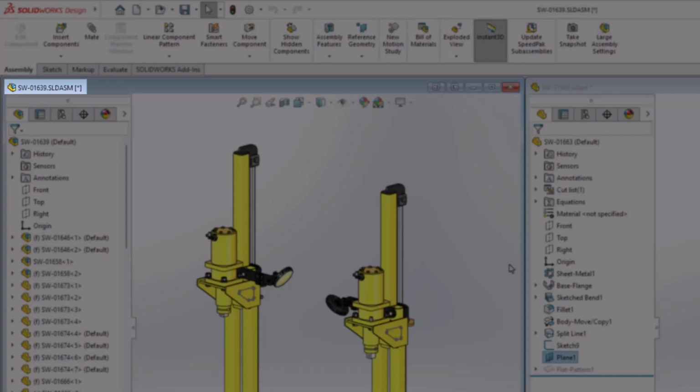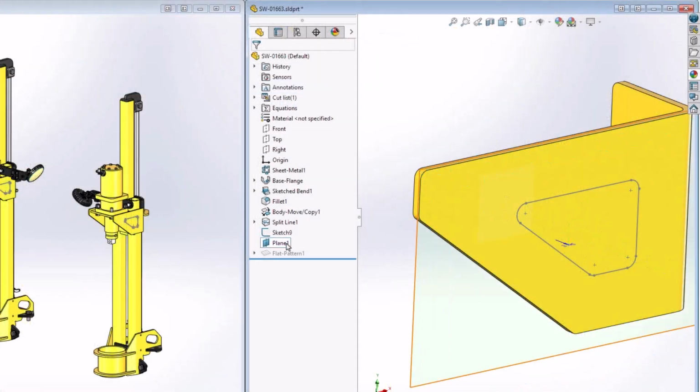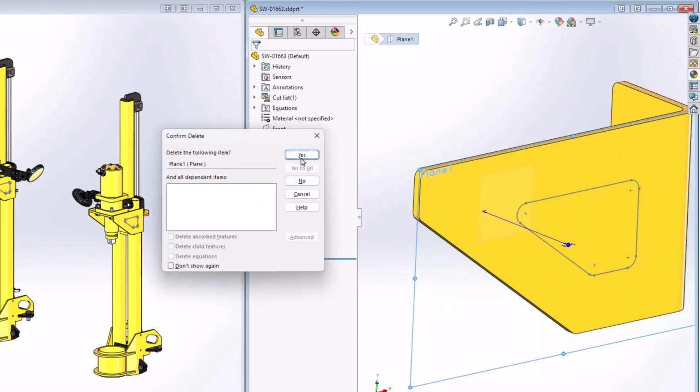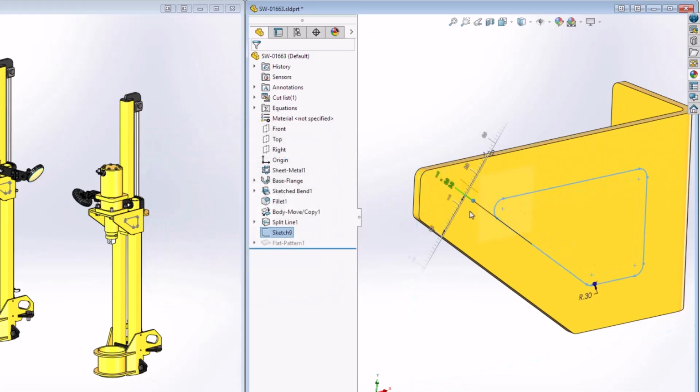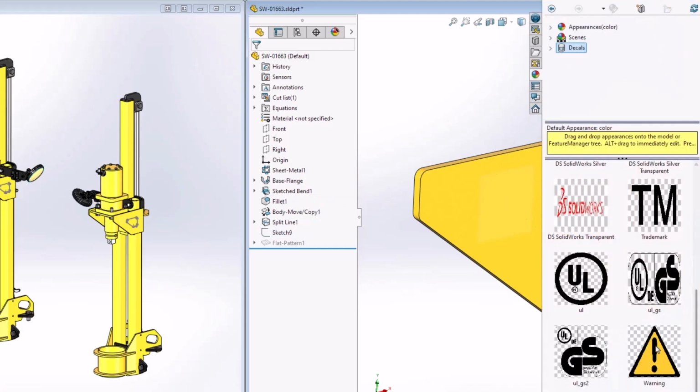However, we are not limited to only creating reference geometry. This enhancement also supports modifying reference geometry, or hiding reference geometry, or even deleting reference geometry, as long as it doesn't drive downstream features that would make non-cosmetic or physical changes to the component and assembly. Other supported operations include creating and modifying unabsorbed sketches or hiding or deleting them. Decals are another good example.